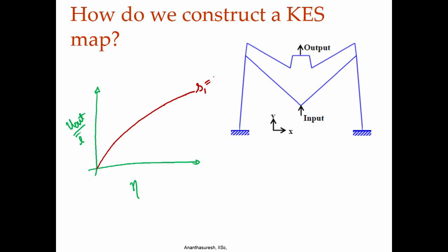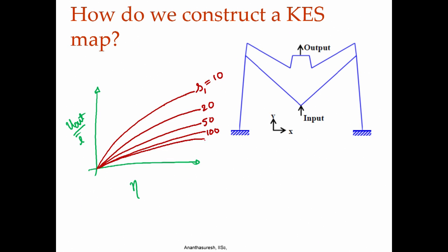For S, usually we start from 10, because below 10, as we already discussed, it does not obey the beam theory on which this non-dimensional analysis is based. So, we take 10 and then increase the value, do another finite element analysis and do it for 20 and then maybe 50, because 30 will be too close, and you will see even with 100, after a while, even if you do 200 it will come very close. Whatever more than 200 does not really make sense, because it will become too slender. So, if I were to do 10, 20, 50, 100, 200, I just need to do 5 finite element analyses. It may look like a lot of work, but only 5 nonlinear finite element analyses is all you need to do for a given mechanism, for this non-dimensional displacement that you want.